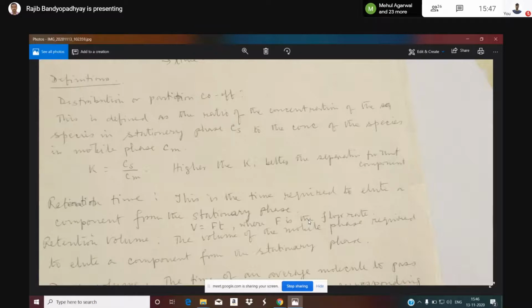So a chromatograph consists of the following parts or components: one, a carrier gas supply with a pressure regulator and pressure indicator. The carrier gas comes with some pressure, and the pressure is quite huge for a packed column, and it's much less for the capillary column. Then you have the sample injection system. Here, this is the injection system.